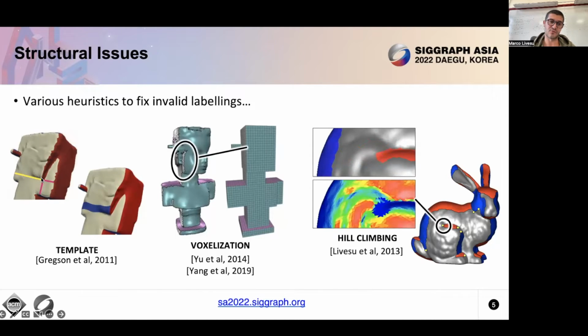And this line is going to be a straight line. So if I make this wiggled line straight, I'm going to introduce a lot of distortion, because I'm opening this wedge until it becomes a straight line. This is not a good polycube mapping, because when I compute my hexahedra and bring them back, the mesh will be horrible.